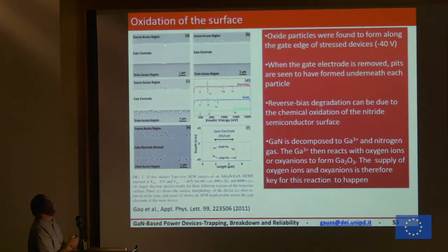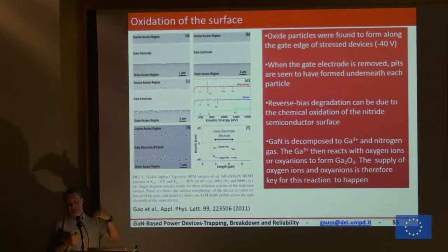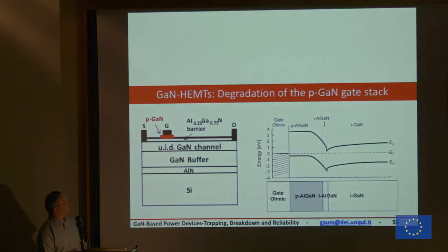They did not see any degradation, while the same device stressed in the same way in an ambient with a lot of atmosphere, with a lot of water and humidity, they found this degradation became more and more evident. So this is something I really believe. It was not really the electrical stress itself that created the damage, but the combination of electric field and ambient condition. So with a very good packaging, you may solve this problem. But at the end, this was a very nice exercise.